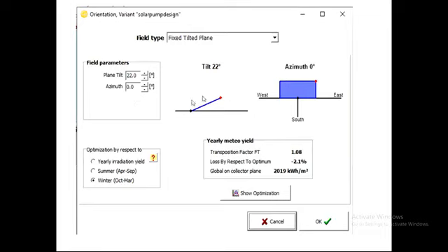Okay. So how can you choose the tilt angle? Tilt angle is equal to your location latitude. So if your location latitude is some 18 degrees, then increase or decrease the latitude and check whether the energy collected by the solar panel is increasing or decreasing.